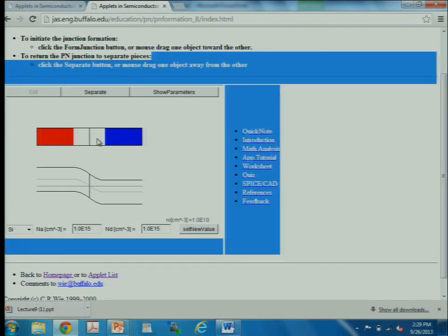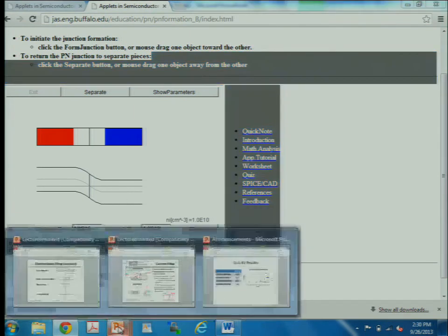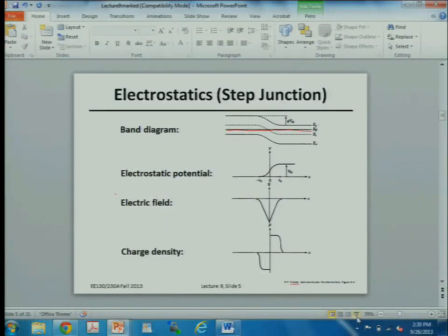On the right, it's n-type. So is this positive or negative charge on the right in the depletion region? Positive, that's right. So you have positive ionized donors on the right in the depletion region, and negatively ionized acceptors on the left in the depletion region in the p-type region. So in the end, the Fermi level is constant in equilibrium. But in order to get the Fermi levels lined up, you have to introduce some band bending. In other words, a voltage drop across the junction. So that's what's shown very quickly here.